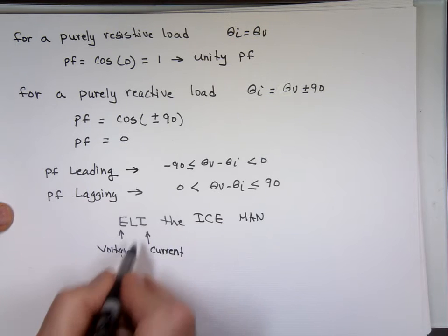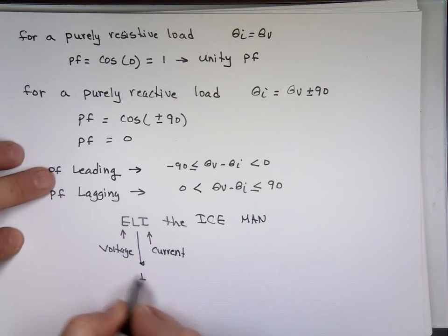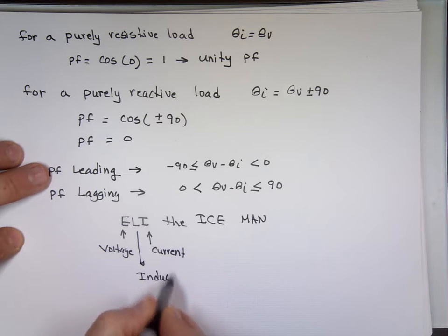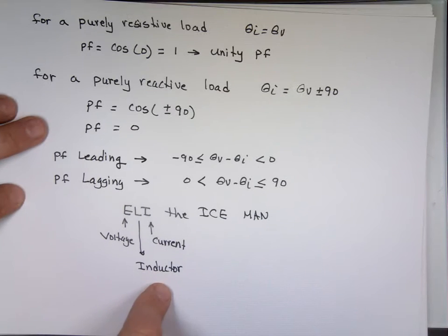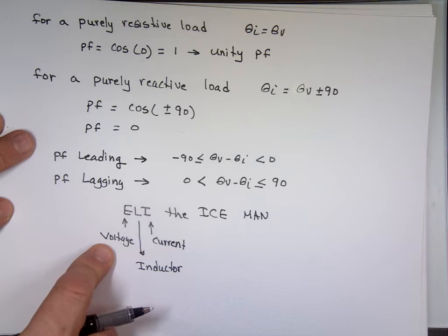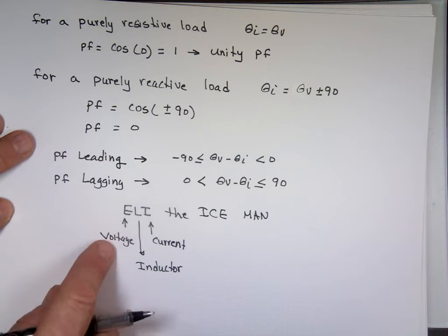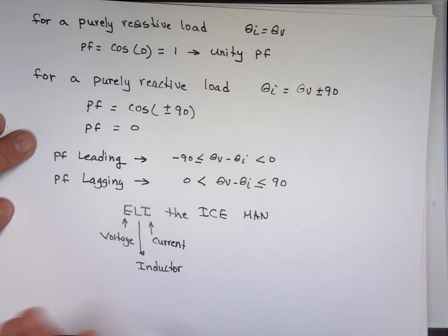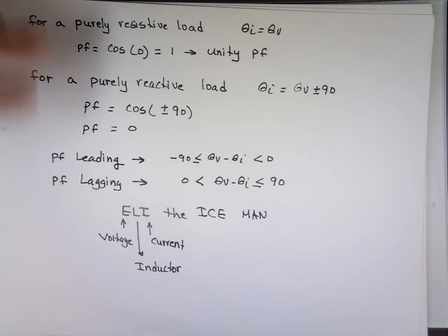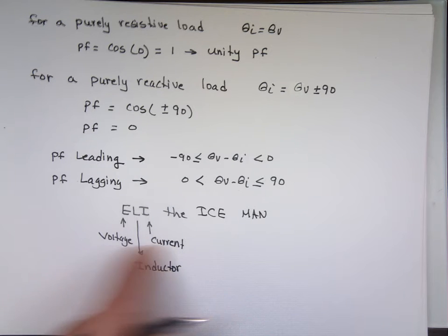L is what? Inductor. So in the inductor, who comes in first? Voltage, before the current. The voltage leads the current. When you ask about the power factor, it's the relationship of the current to the voltage. So the current lags the voltage.